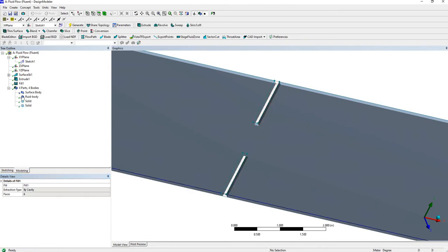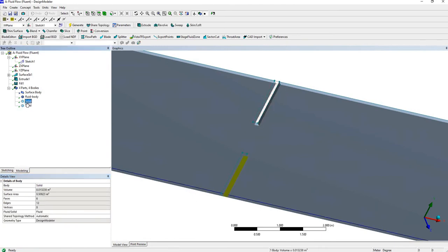Let's click generate. So I have one solid body in here and another solid body in here. Okay, so we have everything. I'm not gonna make connections, like creating one part from all these bodies, because we're gonna do an FSI simulation where CFD data will be transferred to the solid and then we'll do the solution. So let's see how we can do that.